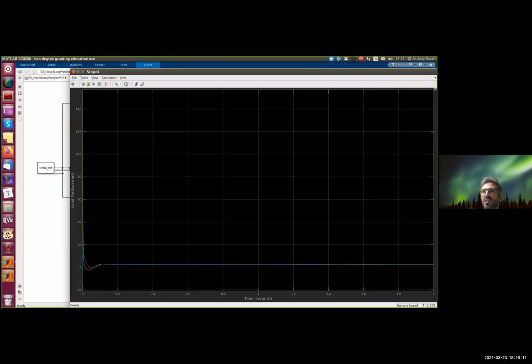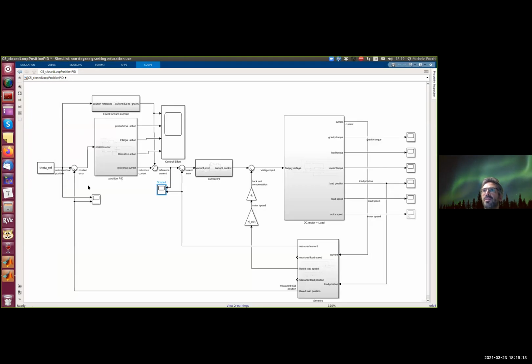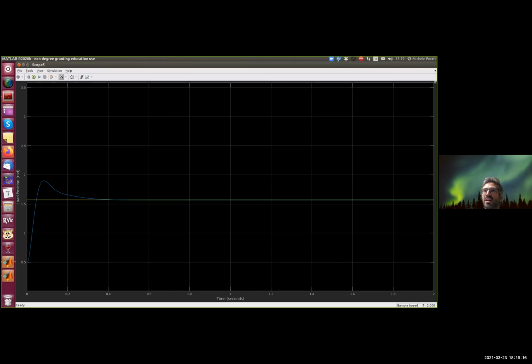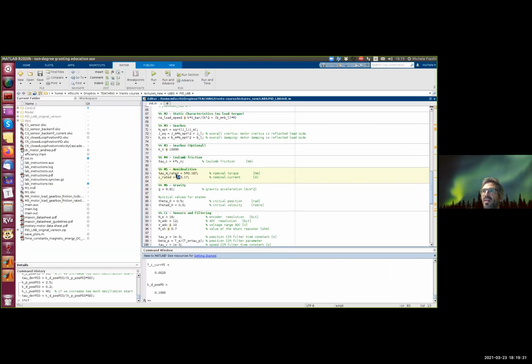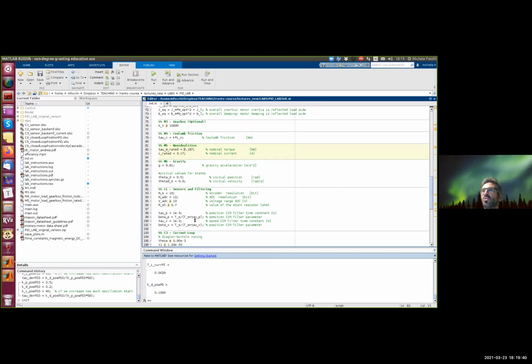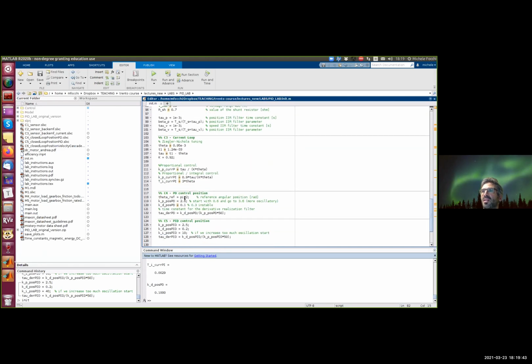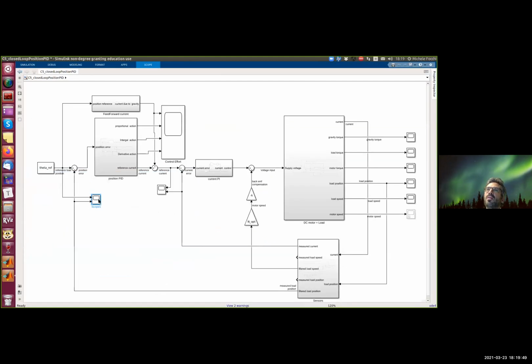We see here now there is no longer a saturation. Let's look at the response. It's much nicer. So that bad response was due to the saturation of our actuation. So what we do: either we buy another motor, so we have a better current rating and torque rating, or we need to accept a slower response. So we reduce the gains, the proportional gains, integral gains. We will have a slower response, but we cannot have both things.